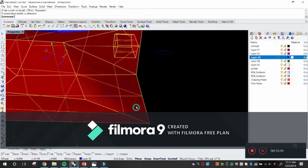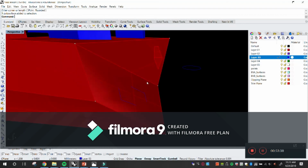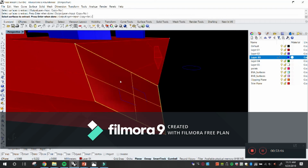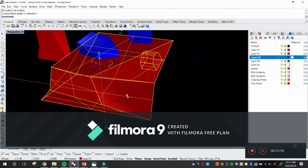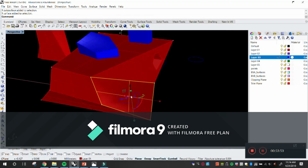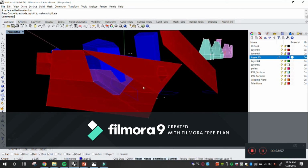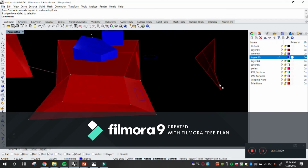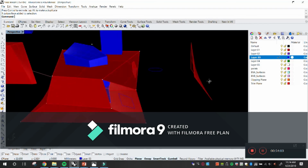The way that you could fix that, and the way that we probably should do it, I don't know if you guys know about extract surface. So right click there, we select the surface, right click, and notice that everything else is still good, but this one has been extracted. What does that mean? I can then lift it up, and I have opened it. Now again, here you can very clearly see how this form bends.